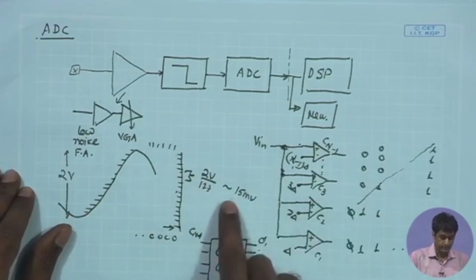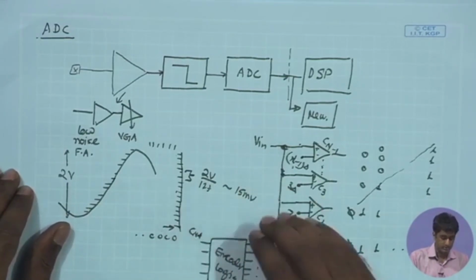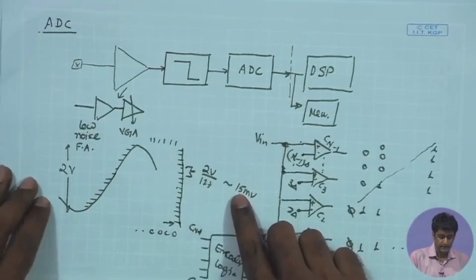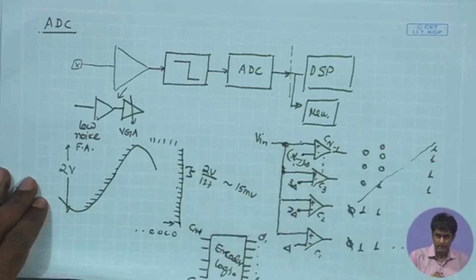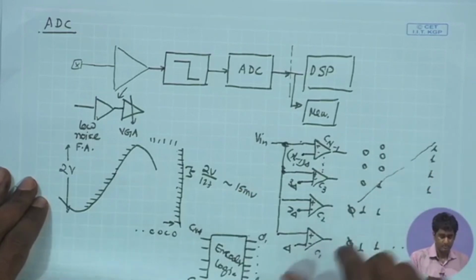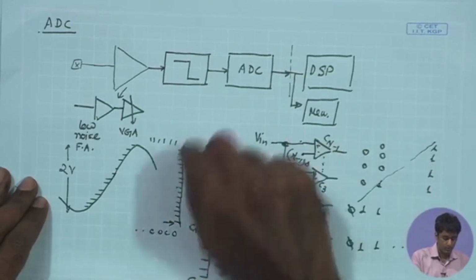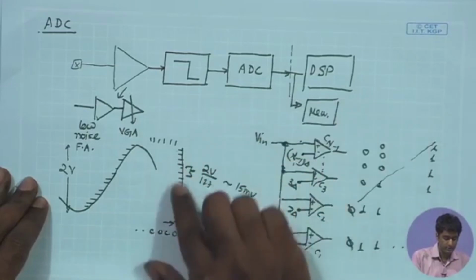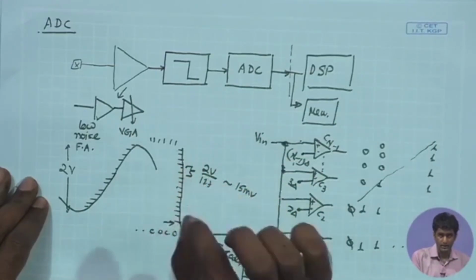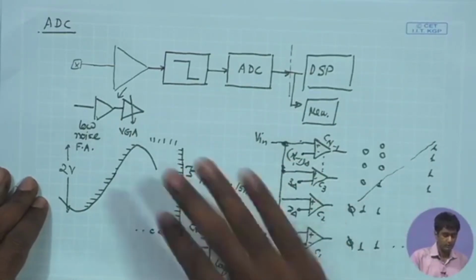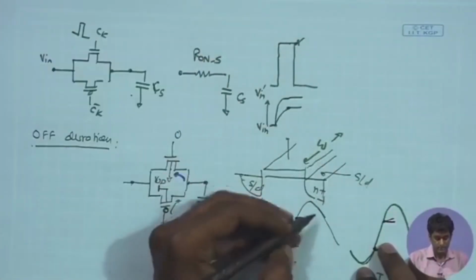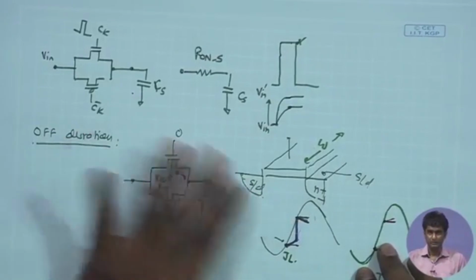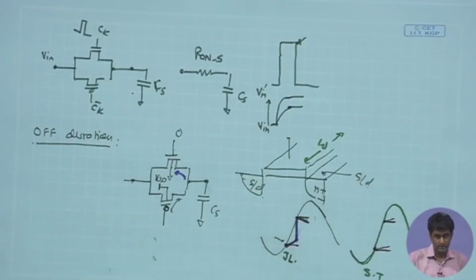That means, if the data droop or the analog droop, or increase in the sample values, is close to 15 millivolt, we are losing 1 LSB of the precision, and we are going to get data which is wrong by 1 interval. That is not desirable. We are going to lose 1 LSB of information. So, we should make sure that this droop or increase that is happening because of the leakage component is lower than that 15 millivolt interval.